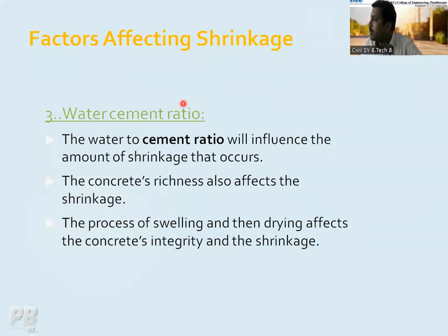If water is available with you, then you can use water. If it is not available, like for big structures, they are going to cure that particular structure with different techniques. Like membrane curing is there, then gunny bags are there. Wet gunny bags we are going to spread.